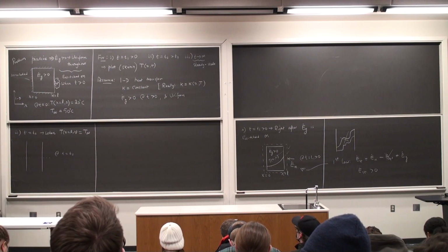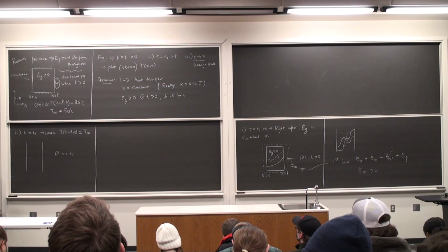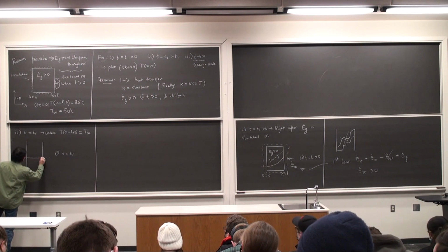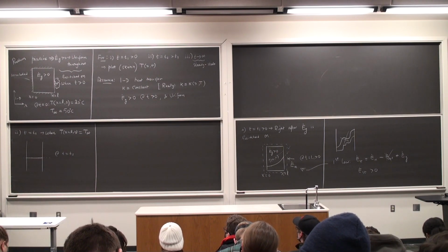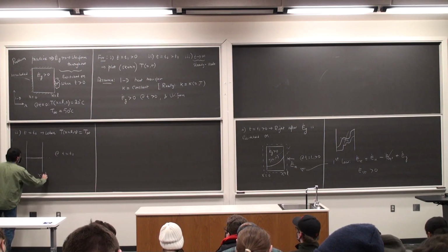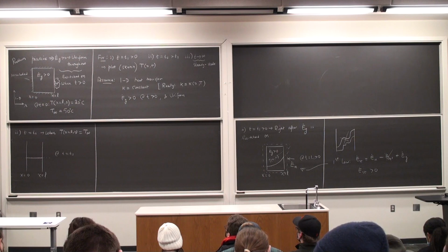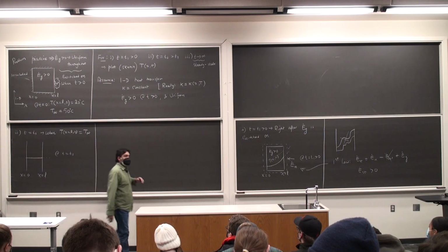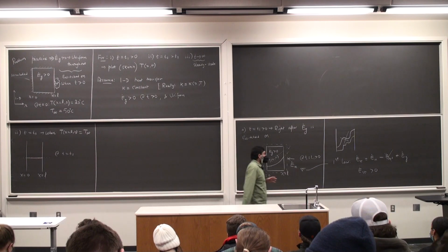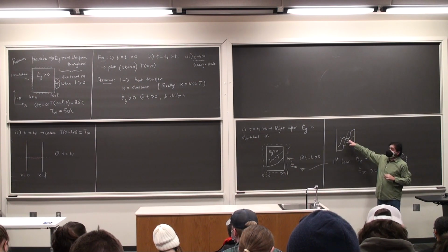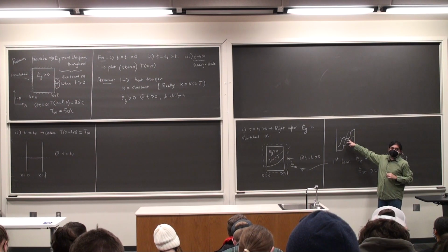And so at this special time, my temperature is going to be the same throughout. This is the x equal to 0 side, x equal to L side. Because we are assuming uniform volumetric energy generation and constant thermal conductivity, I cannot have funky things taking place within the material.